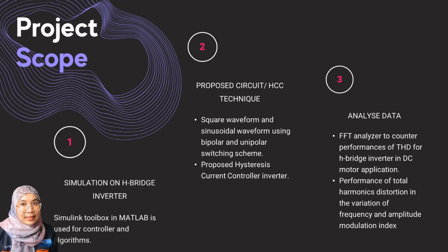Third is to analyze data using FFT analyzer to count the performance of THD for H-bridge inverter in DC motor application, and performance of total harmonic distortion in variation of frequency and amplitude modulation index.